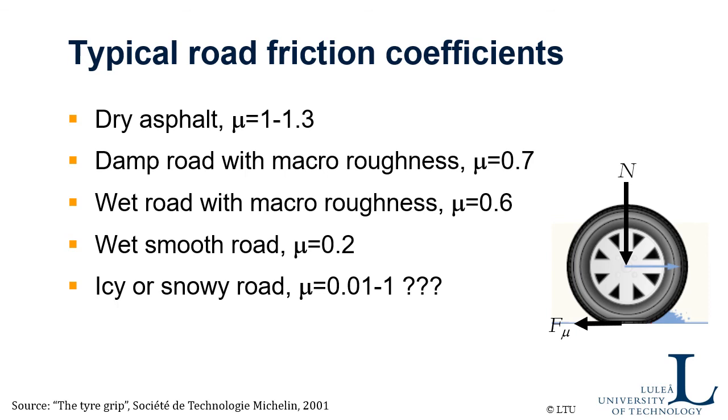And then taking also into account that, apart from the hysteresis effect, you also have the effect of water. So if you have a perfect rubber and dry, no water available, the friction coefficient will be very high. It's well above 1. But as soon as you get some damp or some water on the surface, still with some roughness on the road, you reduce the friction very much.